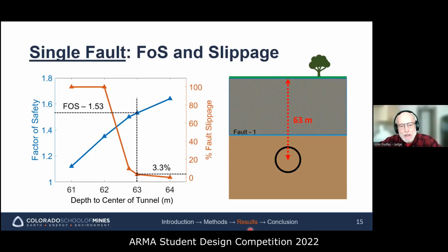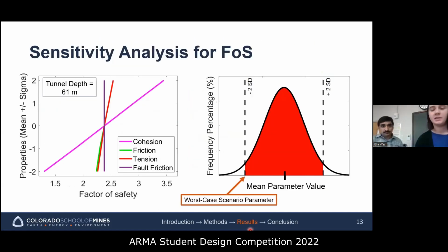Second question. You did Monte Carlo simulation. Did you include the Young's modulus and Poisson's ratio in that? No, we didn't. Only the strength parameters. Only the given parameters were used for the Monte Carlo simulation. Other than that, what we assumed were the dilation angle and the Poisson's ratio, which I mentioned came from the initial code, and were not used as parameters for the Monte Carlo simulation. We didn't have the standard deviation information for those either, so we just stuck with one value.